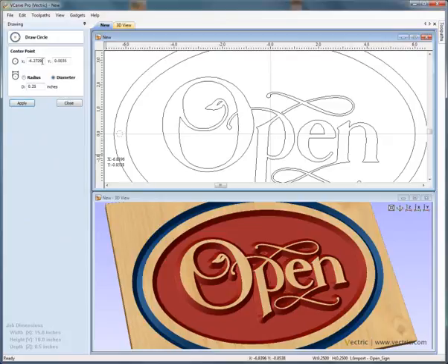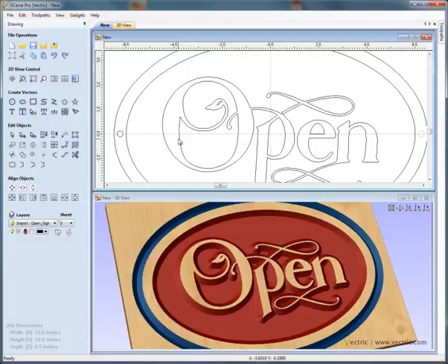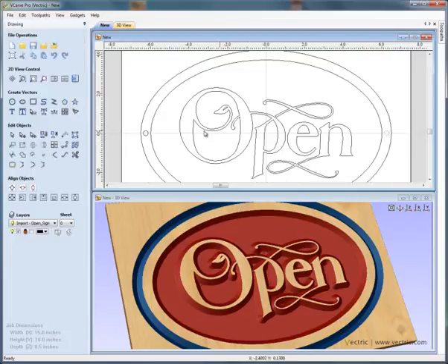While we've got this one selected, if I say this circle needs to be at 6.25 inches negative in the X dimension and on the Y axis, and apply, it will jump to the exact position. If I click on the right hand side, we want this one to be plus 6.25 inches and also exactly on the Y axis. So apply again and it's jumped into position. Close the form.